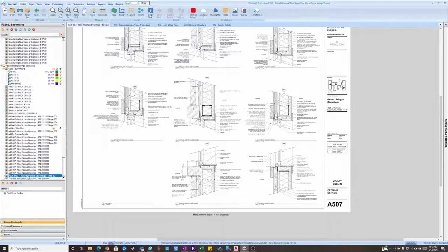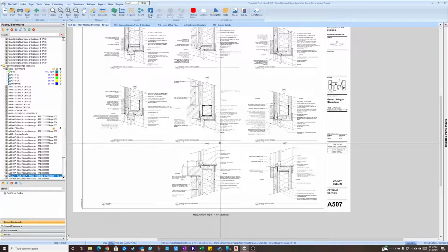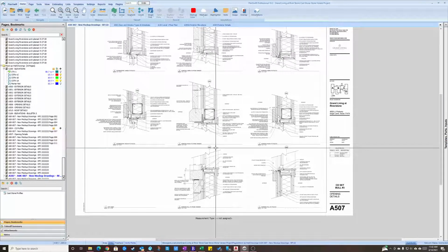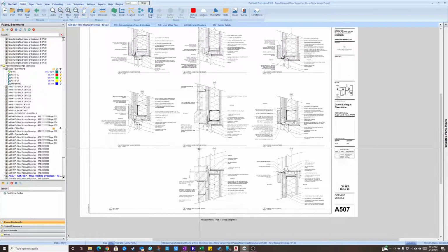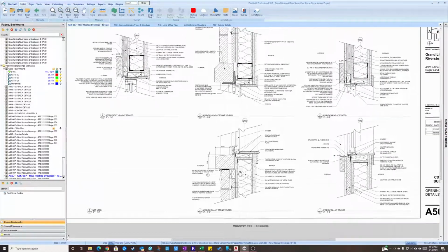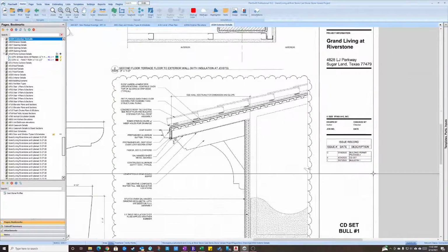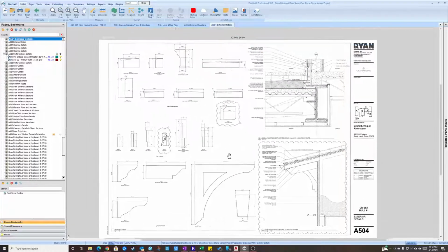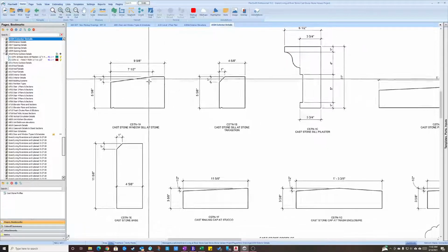Let's do a little bit of legwork here because, and I know this isn't the easiest set of drawings to start with, but we got to start somewhere, right? This is not typical. This is a big job. Typical shop drawings are going to be easy peasy, water tables, things like that. So I've noticed a problem here, and the problem that I noticed was that if you go to the profile page that we just looked at, which is supposedly the newest set, they're saying that the window seal is 9 5/8.